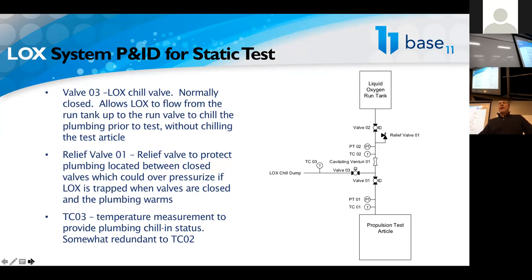So in designing the liquid system, generally speaking, we're designing for velocities that minimize the friction pressure drop to a manageable level. But it's a good point with respect to the velocities. LOX systems will have gaseous oxygen in them until they are cold.